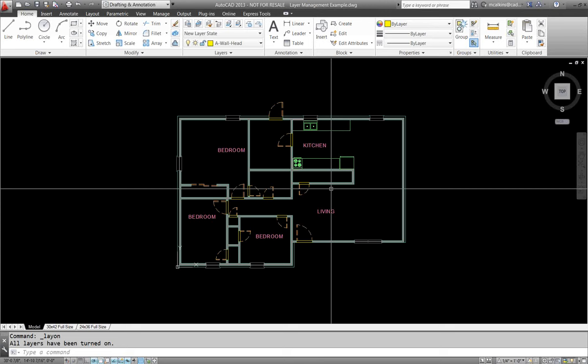then create one for your floor plan, any of your different types of drawings that will be generated from this file, dimensioning plans, furniture plans, I don't know, demolition versus existing, or proposed versus existing, whatever it might be, any of those kind of things that you use a lot of layer management for, save it into a layer state. The other great thing is that you can save that.